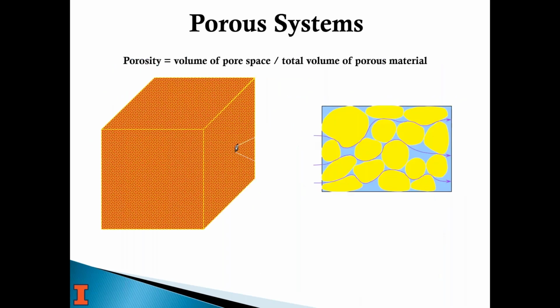So we're going to talk a little bit about how water flows through the ground. And this is covered again in some of the early lessons of our class, but there's really two concepts that matter here. One is where's the water at in the ground? This block is meant to be a block of sand. So the yellow circles there are sand grains, and the water exists in between all the spaces. So if you had a jar of sand, the porosity, which is the airspace, is close to 30% if it's uniform sand. So in an aquifer that's underground and it's completely saturated, that 30% is full of water.